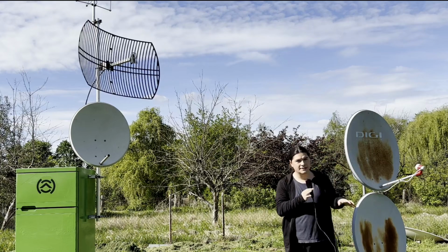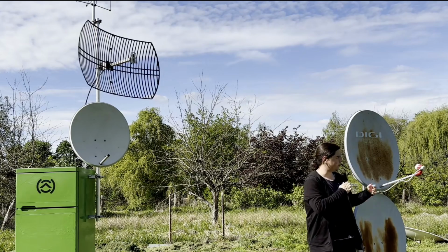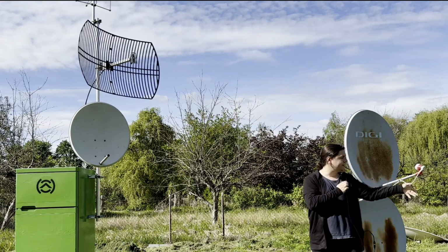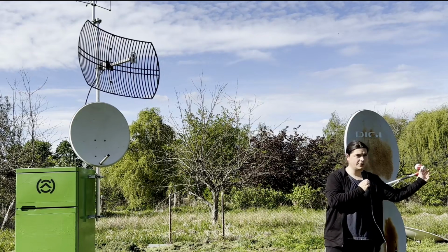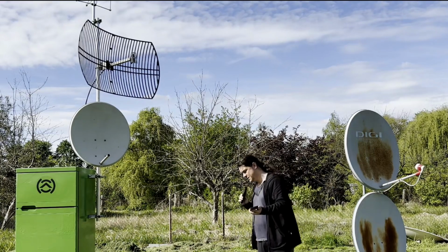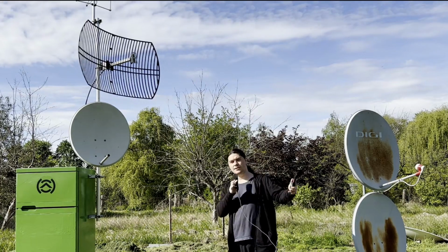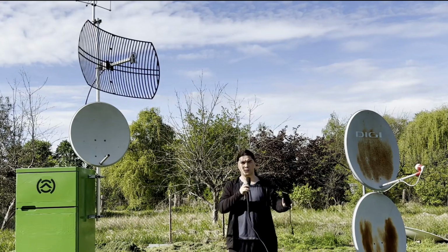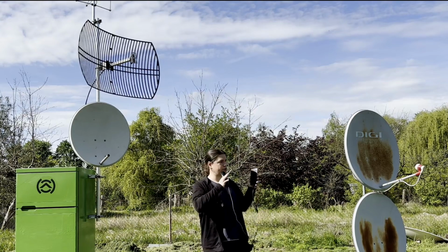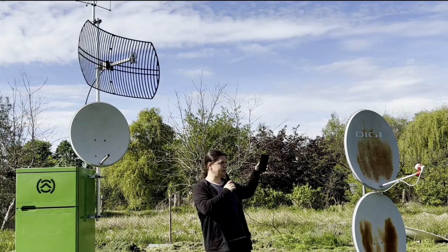When you do find a signal and you maximize its strength by aligning the dish antenna, the last thing you can try doing is slowly rotating the LNB and seeing at what orientation is going to give you the strongest signal. And I think I have sort of talked about everything there is to the actual reception of the satellite, right? So I'm now going to hand it over to me from 2 days ago, and we're going to go over the software setup to actually show you how you can compensate for the frequency drift of your LNB in software, which is actually really important.